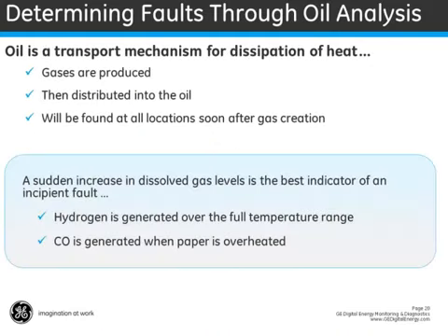So how is this possible? How can we be sure that dissolved gases in the oil are produced by fault and have not simply accumulated due to oil aging? And that is where the years of experience utilities have gained in tracking DGA comes in: mapping DGA results to faults during transformer repairs or even during postmortems.